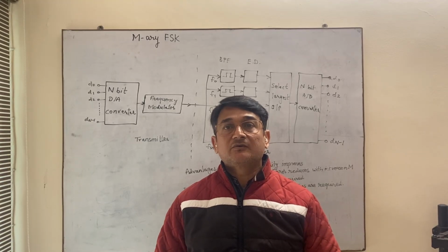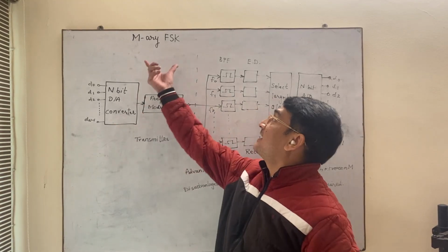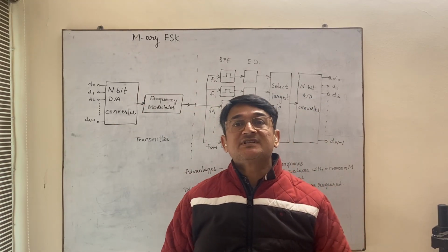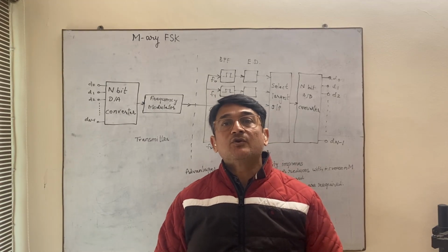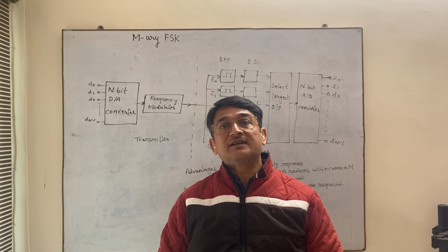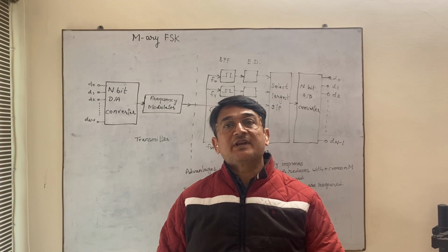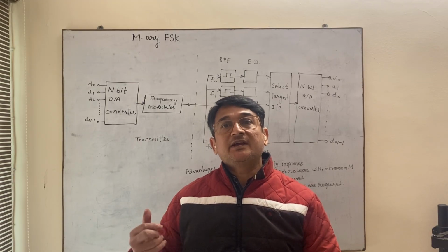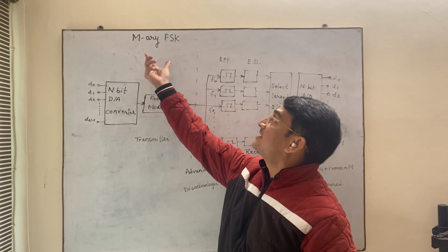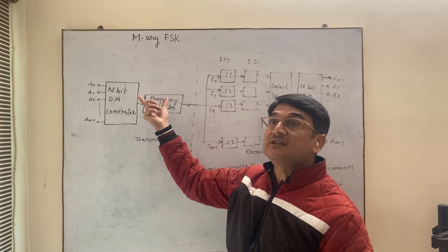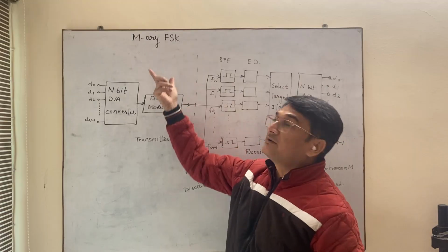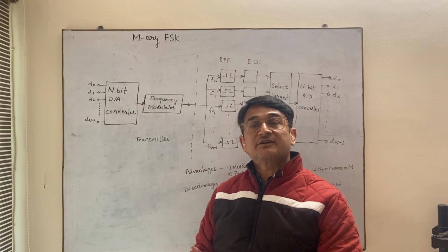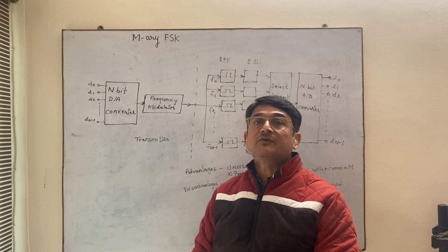In this video, we will understand the concept of M-ary FSK. Previously, we have understood the concept of M-ary PSK. As I have already told you, there are two M-ary signaling schemes: one is used for M-ary PSK and the other is used for M-ary FSK. In M-ary FSK, that is M-ary frequency shift keying, there are M different symbols to be generated, and corresponding to each different symbol you have a different frequency.